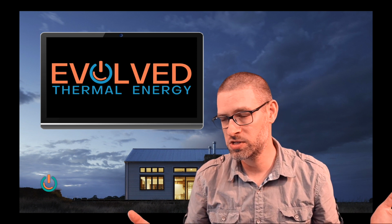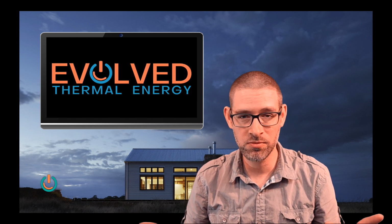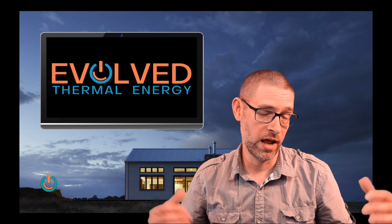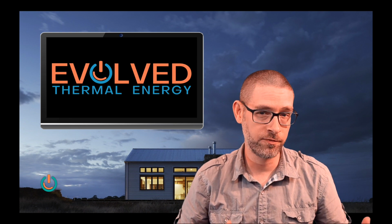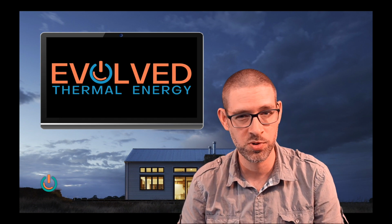Let's say we're using that at 16 cents a kilowatt hour. That's the peak time of use rate, I think, around here right now, and that varies. And actually, studies have been done to show that with ground source heat pumps, my heating system is going to operate mostly off-peak and mid-peak. So I'm being conservative here. That's about $1,400 per year.